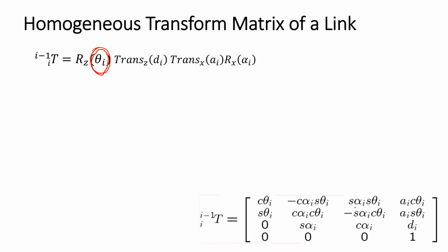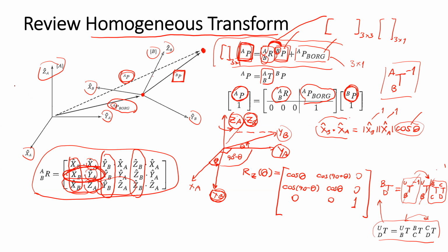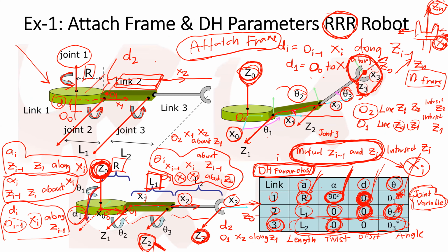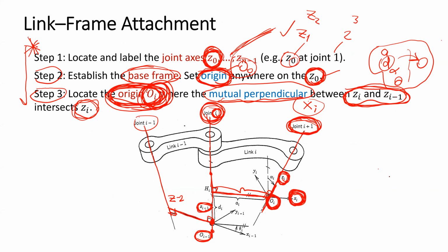So the step, the homogeneous transform that shows the relationship between, maybe, frame 1 to frame 0. From frame 1 to frame 0, we derive the Denavit-Hartenberg parameters. We know the link length, link twist, offset, and angle. The meaning of the parameters comes from here.